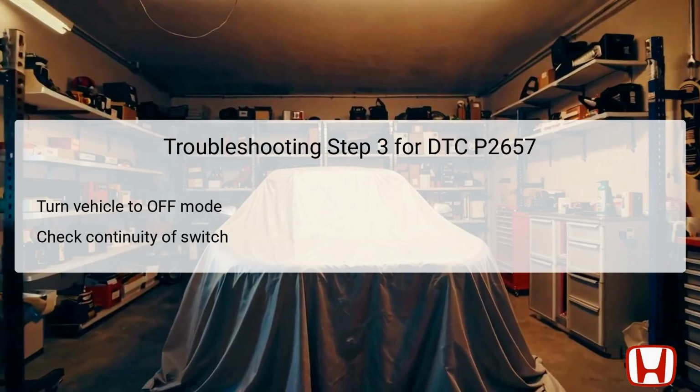First, ensure the vehicle is turned to the off, lock mode. To safely conduct this test, disconnect the rocker arm oil pressure switch A bank 2 2P connector to isolate the switch from the circuit. At this point, continuity must be checked between the designated test points within the connector. Test point 1 corresponds to the connector's number 1 pin, while test point 2 corresponds to number 2 pin on the switch side. A continuity reading confirms that the switch is operational, permitting you to proceed to further diagnostics.